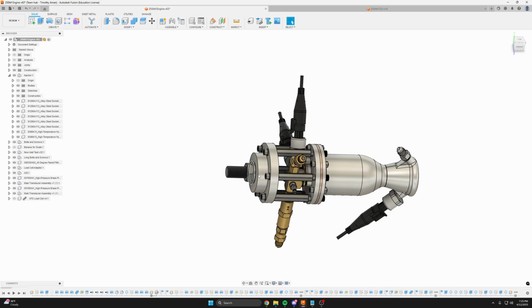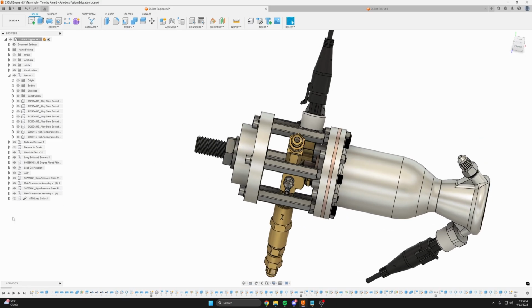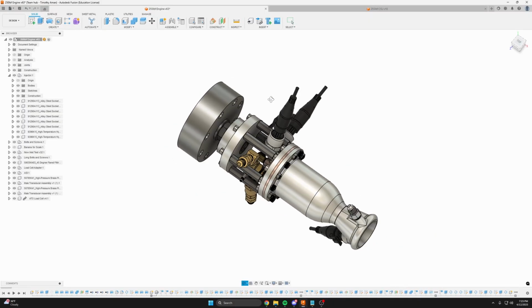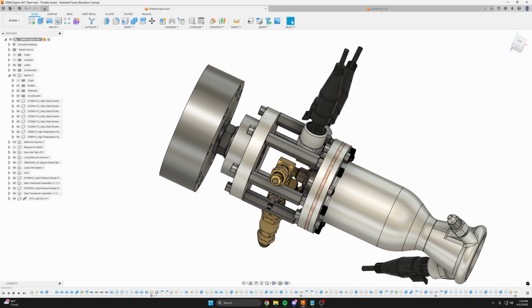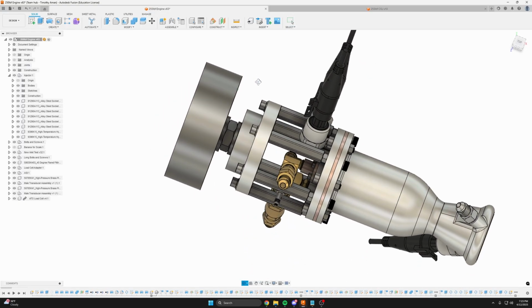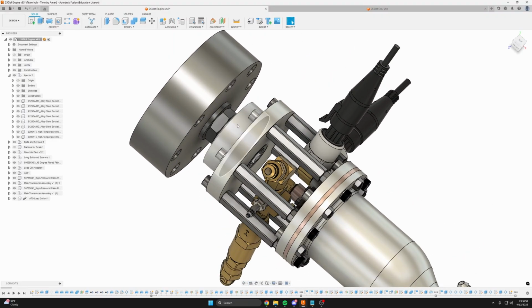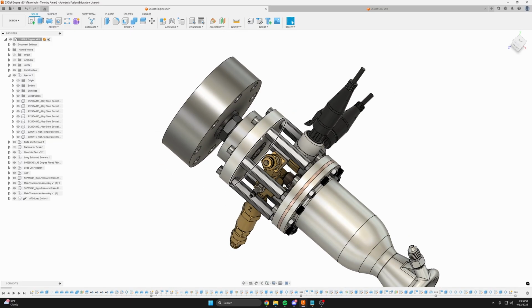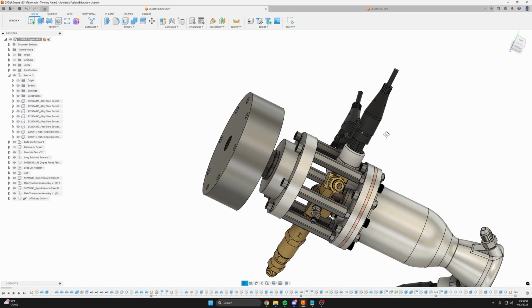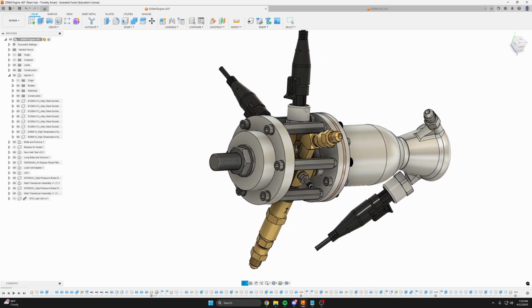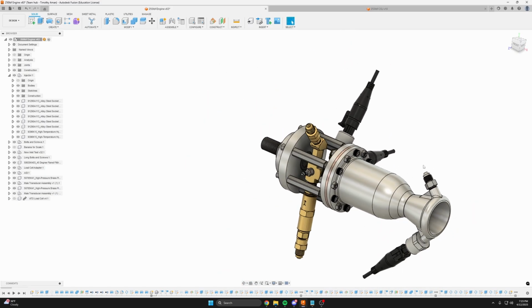We also have this load cell adapter that threads into a pancake style load cell. That's good for taking force measurements. For small engines, this is how I would recommend doing it, a pancake style, for small to medium engines maybe. Once you get past a certain size, I don't know if one single bolt would be the best way to do that, but there shouldn't be any significant side loads. So that's how you could take some force measurements for your engine.